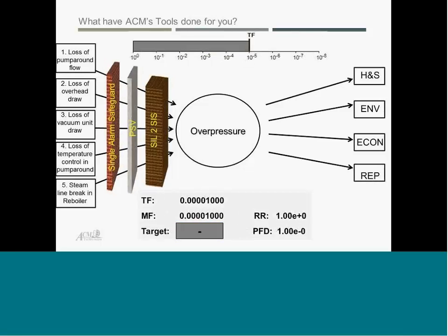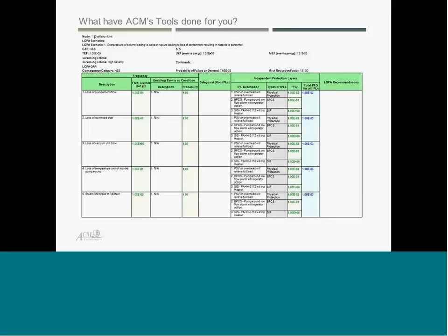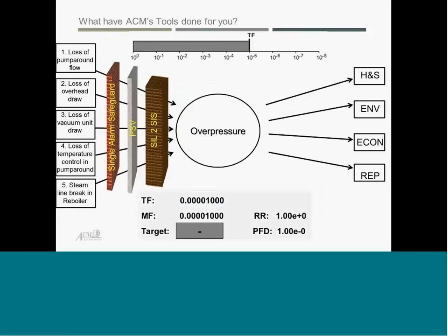Next, SafeGuard Profiler helped you actually analyze your scenario, both in reducing the number of alarms and making your mitigated frequency match your tolerable frequency. It told you what that SIF reliability needed to be. Compared to a spreadsheet, you can analyze 4 times quicker or even more, depending on how many consequences you have, because you can analyze more than one consequence at a time in a method that's simpler for the team to understand and gets you better results in the end.